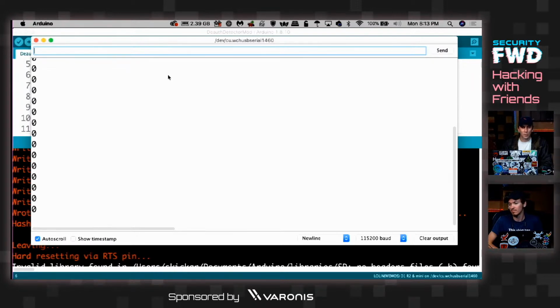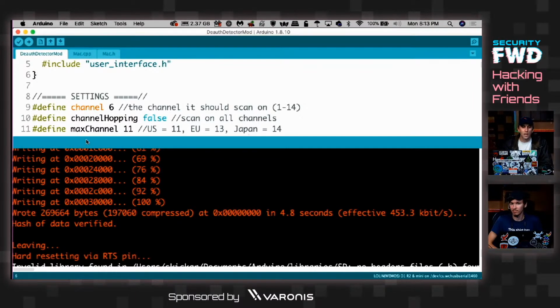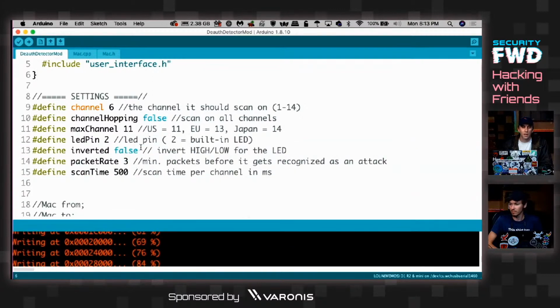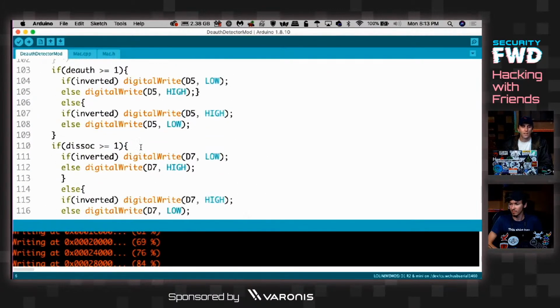Because this is the correct response we're looking for. So if you're following along with an old ESP8266, or if you're watching this later, and you're just getting a bunch of zeros over serial with the baud rate set to 115200, then you should be good. And here I am connecting to a couple different pins. Let me double check in my code which ones I'm connecting to. All right, so if I get a deauthentication packet, I'm connected to pin D5.